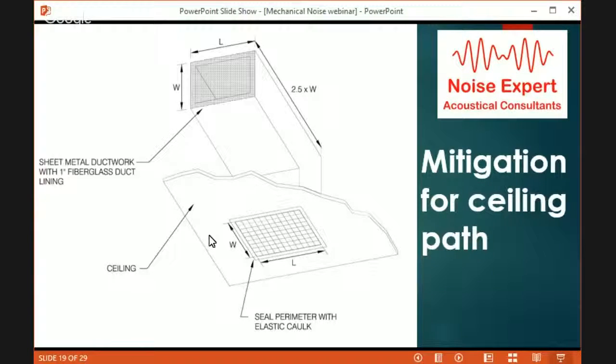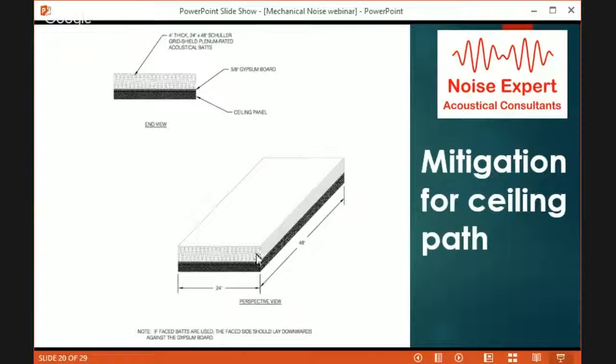And if you have a very absorptive fiberglass ceiling, noise can pass right through it, even though it'll absorb the noise in the room from people talking. Any noise impacting this will get either absorbed or transmitted up into that ceiling plenum. There won't be as much reflected, but when you're just talking about mechanical noise passing through, a light fiberglass ceiling tile is not very effective.